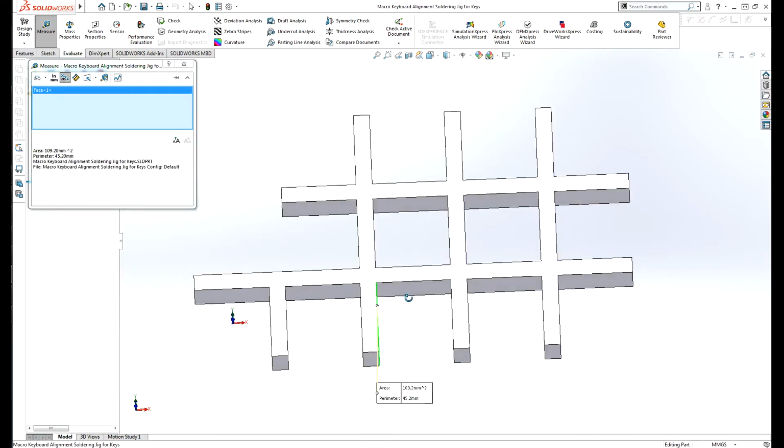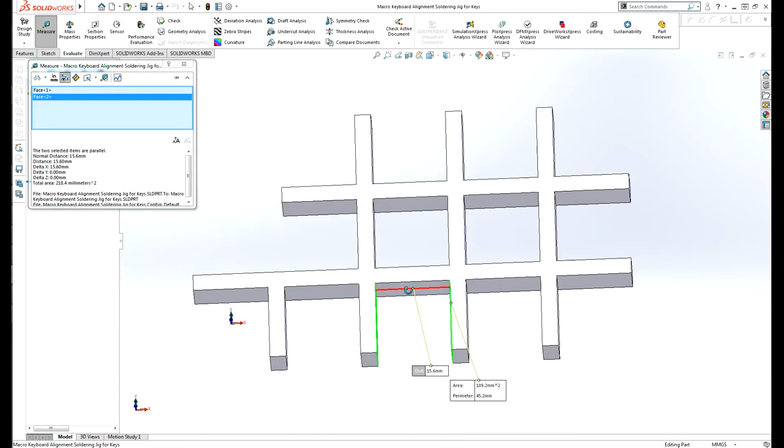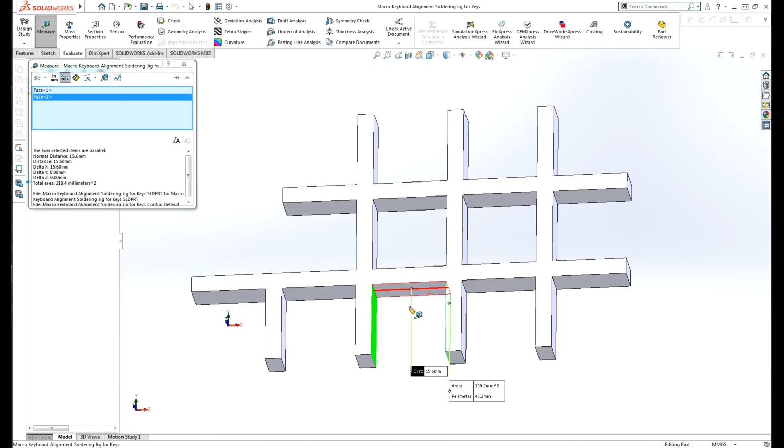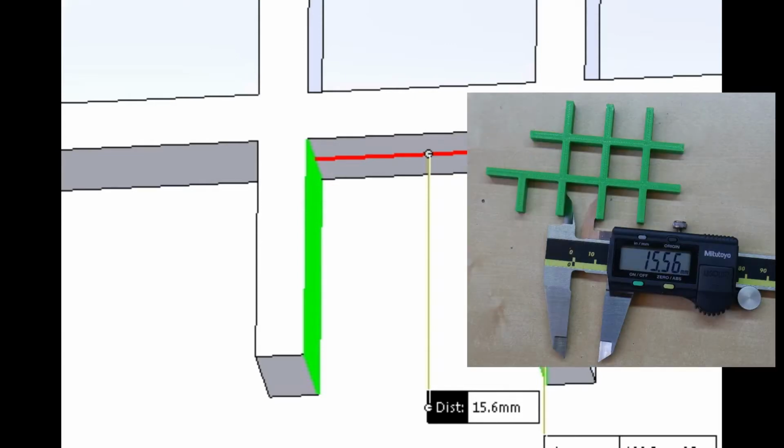Regardless of the file format you pick, note that most fused deposition model-based prints will shrink. Your model is printed with hot filament or plastic here. Once cooled, said plastic will shrink. On average, parts typically shrink by 1% when using PLA-based filament.